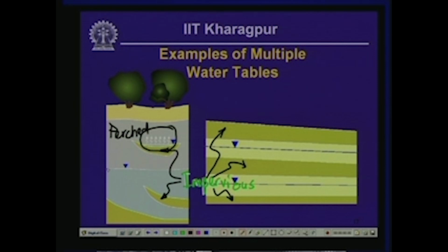You can have another groundwater which is exposed like that, which has got a surface which is below the surface of the zone of saturation or water table, like that. So that is called an unconfined aquifer actually. So this one is an unconfined aquifer.